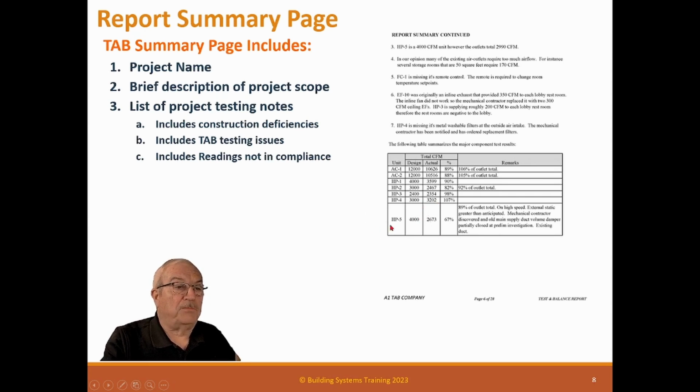But what these people, who have obviously never done balance, fail to realize is that our instruments have certain accuracies, and some of them are plus or minus 5%, some plus or minus 3%, some plus or minus 2%, and some plus or minus 10%. Well, to do a plus or minus 10% job, you need to have a plus or minus 5% instrument. You need to have about half the accuracy you're shooting for in your instrument.